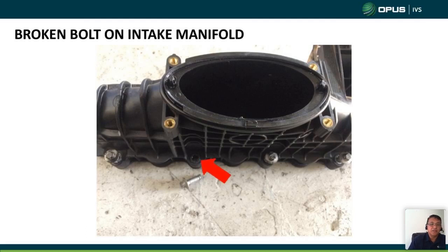And that's the issue there, the bolt for the intake manifold snaps. What I'm thinking, it could be the possibility the engine vibrates, and that's the reason why the bolt for the intake manifold snaps. And mostly it happens in between cylinder 1 and 2.